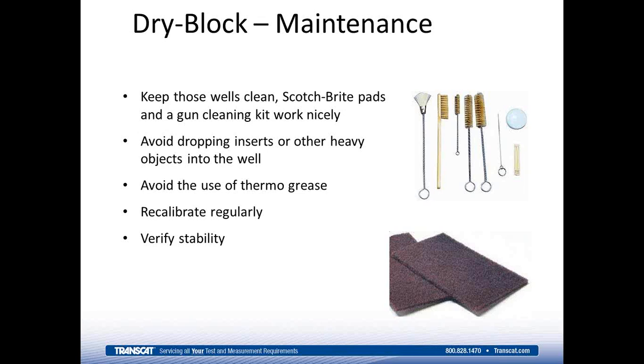So when you're putting an insert in and out of a dry well, you want to use the tongs or whatever device is provided to help you do it. We talked about the thermal grease a little bit. Regular calibration is important, and verifying stability is also important.